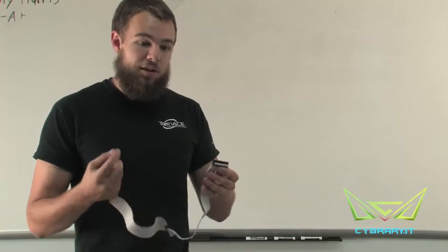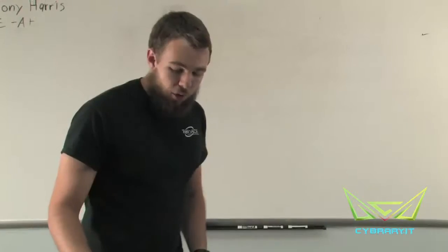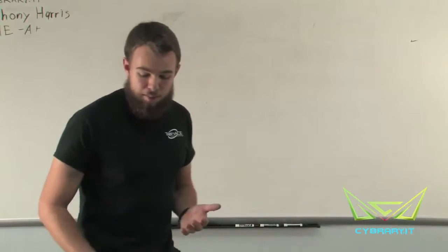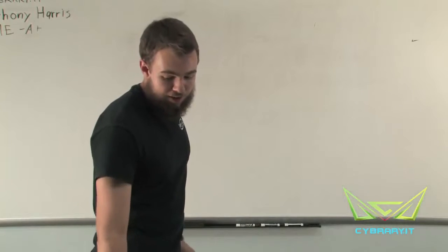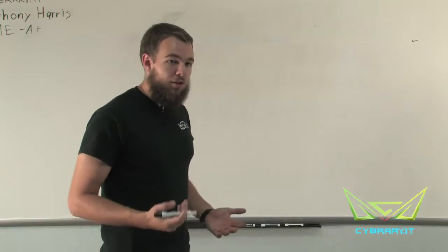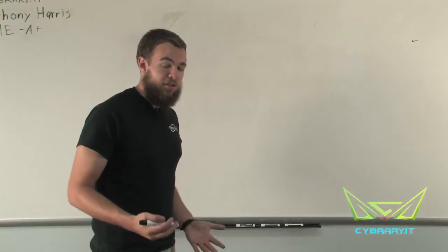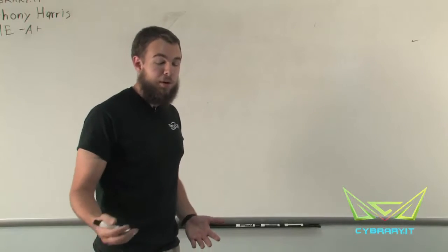This twist is going to be on the end of our last floppy drive. So we don't want to plug in the end with the twist into our motherboard. We want the twist, again, to be plugged into our floppy drive. We don't use floppies too much anymore because we need more space than floppies can allow. But we still use them for recovery, and we still use them in emergency situations, so it's good to know a little bit about the connectors.